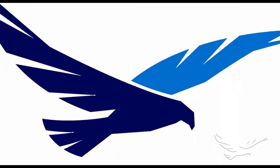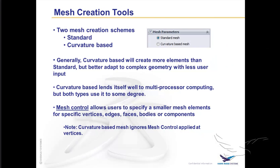Also, the curvature-based mesh really shines at the assembly level or multi-body part level. The curvature-based mesh lends itself really well to multi-processor computing, especially in the volume filling stage of the mesh. And then we'll talk about mesh control as well.